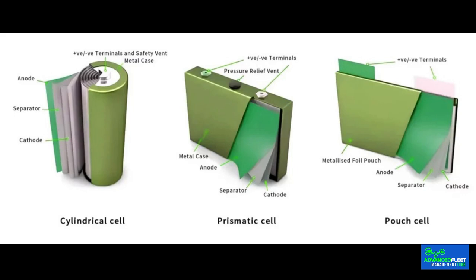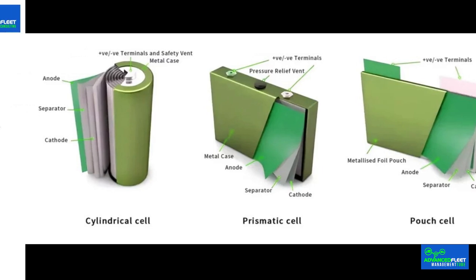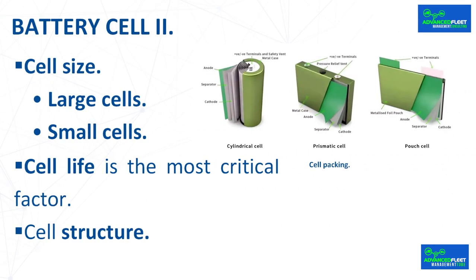And the separator consists of a porous plastic polymer that contains the lithium salt that forms the electrolyte. In addition, the separator prevents both positive and negative sheets from touching each other and causing a short circuit. All these elements are packaged in a cylindrical, prismatic or pouch structure as developed below.